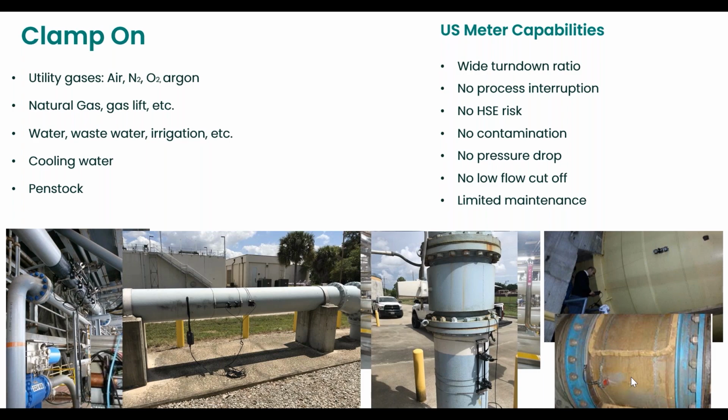So what you need when you have a lined pipe is an understanding of what the thickness is of the two materials. Because during the programming, you will enter the material of construction of both and their respective thickness. Because there are tables in the electronics that say that if I have stainless steel 316 and I have this thickness, I know that the sound will travel at this velocity, so it will take a few milliseconds to travel the wall.